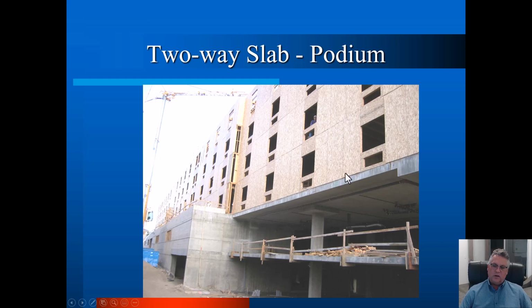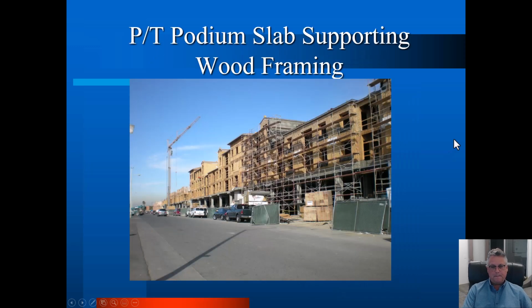This deck is thicker than it appears to be because this plywood is overlapping. But we have a thick deck that we use column caps for because there's a lot of load on these decks. We have a parking deck down below that has no column cap. We just use, which you'll see, stud rails. Very popular type of construction, residential type.